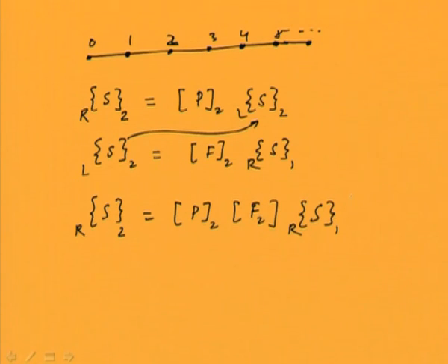So you can see what we have done here, we are now transferring the state vector from right of 1 of the disk to the right of disk 2. So directly we are jumping over the shaft and then disk in one shot, and the same thing can be extended for the whole shaft.